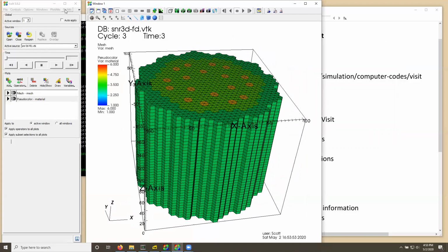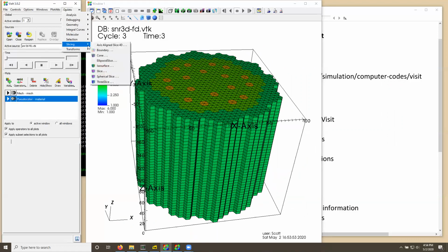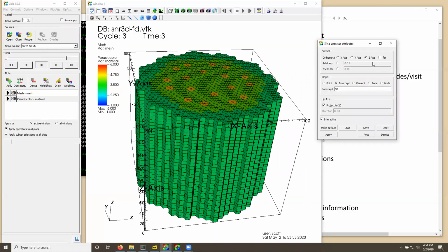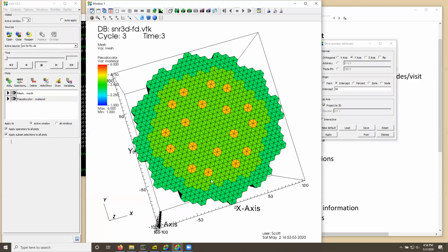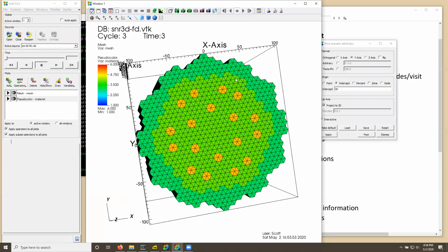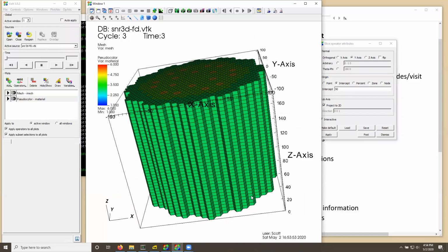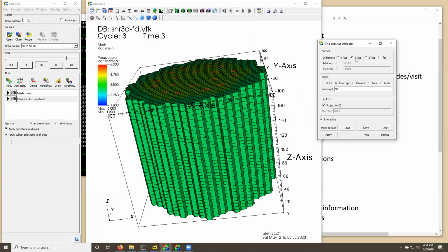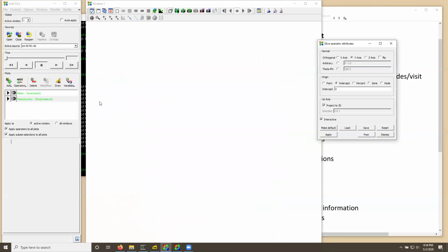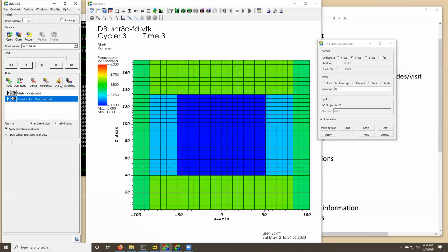Okay, again, go up to operation attributes, slicing, do a slice, but let's do a slice on the y-axis. So instead of taking a radial slice, we're going to look at a slice that's orthogonal to the y-axis. Again, if we scroll around, you can see that the y-axis goes from -100 to 100 approximately. And so we want to take our intercept right at 0. So go to our slice, it's going to be orthogonal to y, and our intercept is going to be at 0 this time, and we apply. Again, nothing happens. Go over to the draw, hit draw, and we get our slice.